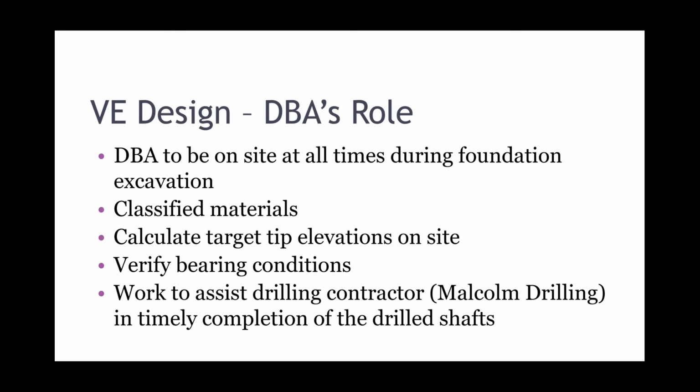So our role after the VE design was submitted and accepted, we were to be on site at all times during excavation, classify the materials, and come up with those target tip elevations on site. Again, in real time, but not on a whim. I mean, we had done our homework. Also, we were there to verify bearing conditions.